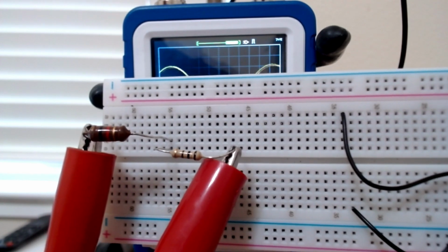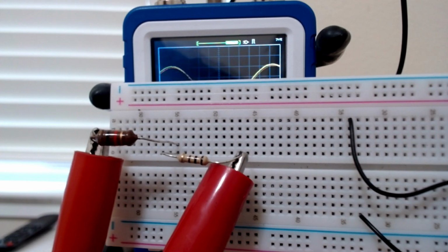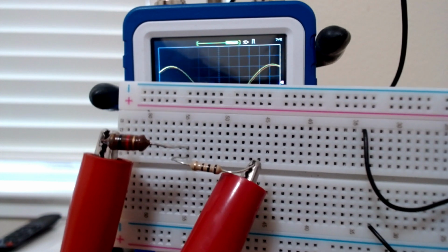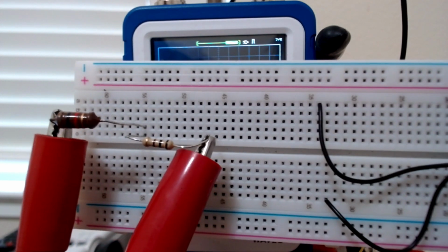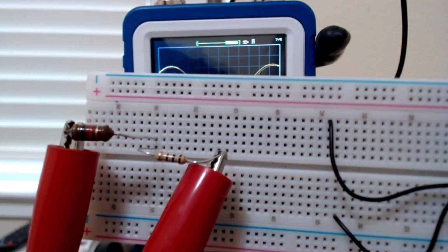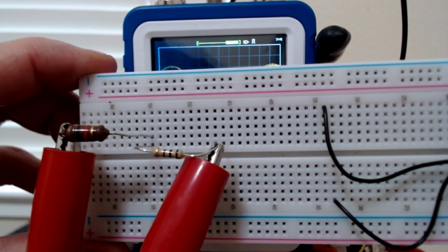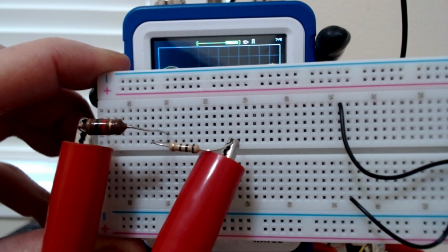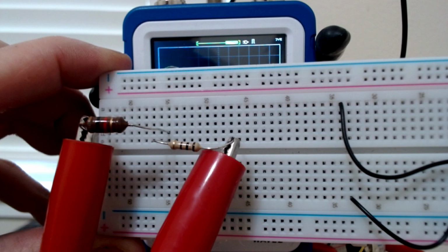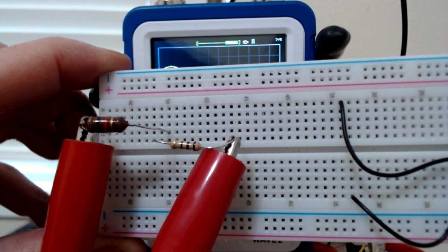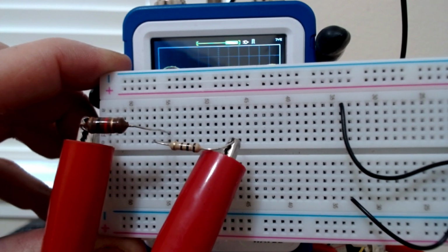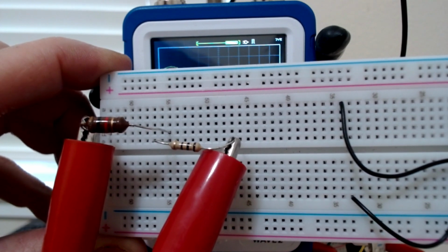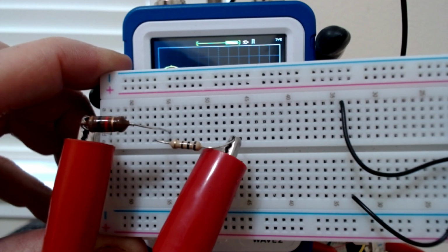Yeah, the one on the left is not a resistor. The big looking resistor is an inductor. Okay, so you should have one like that. It's black, brown, black, red, and gold. It is a 1,000 microhenry inductor, same thing as 1 millihenry. Okay?